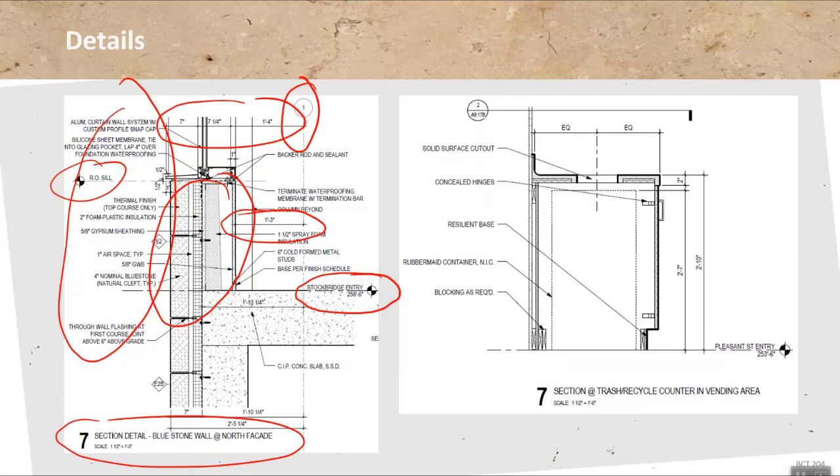There's one thing that's not shown here. Typically, whenever you break material like this, you could show it as shown here, or you may encounter a break line, which is basically this kind of squiggly line, which shows you that you're breaking material, especially if you are showing something in one detail where you're removing the middle. That's where you'll find these break lines. If you see those, they basically just tell you there's more to the right.